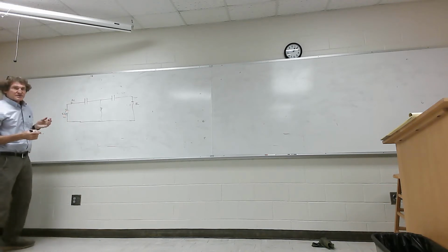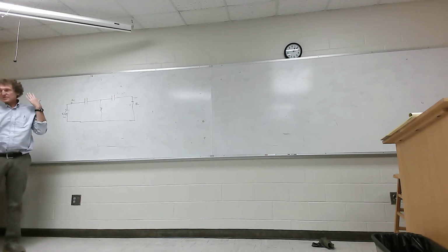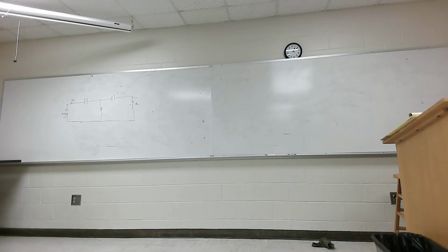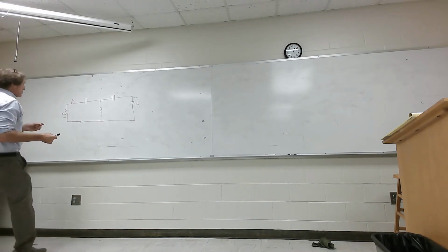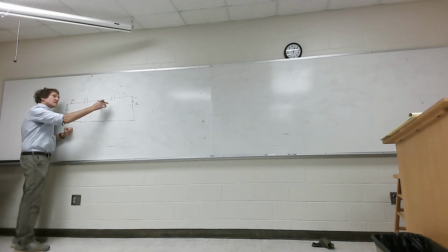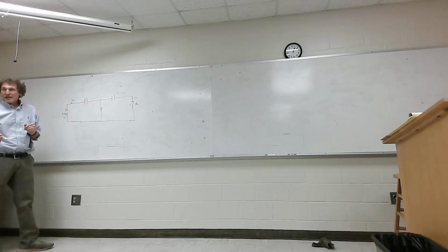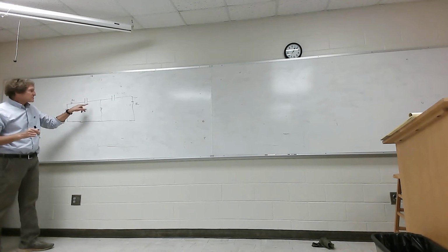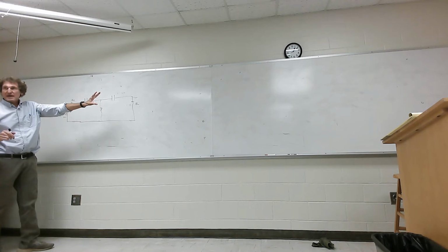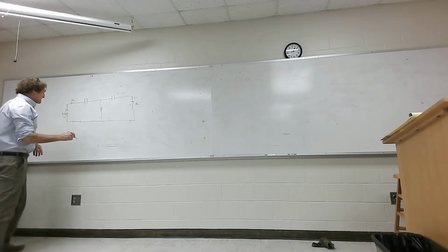Now, if you look at this for a second, just always do this in your mind. Take a look at what this circuit looks like as frequency is 0 hertz and as frequency goes to infinity. So, at 0 hertz, a capacitor has an infinite impedance. Y'all agree with that? That's an open circuit. The output is 0. When the frequency goes to infinity, theoretically, capacitors look like short circuit, inductors look like open. It's definitely, if you think about that, a high pass filter just by looking at it. Y'all follow me?